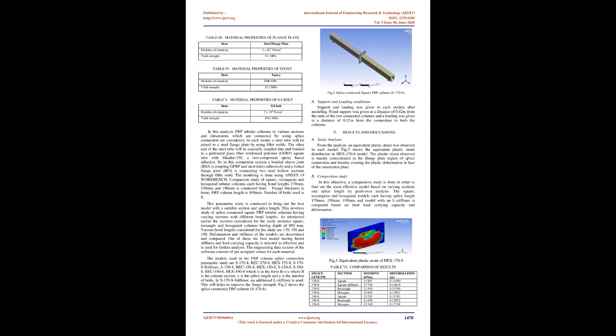After proper modeling and meshing of B170-8, the model is analyzed under pushover analysis. The maximum bending moment corresponding to the maximum displacement obtained from the validation is 9.2 kNm, while the maximum bending moment obtained from the journal is 9 kNm. Therefore, the percentage error obtained is less than 5%.